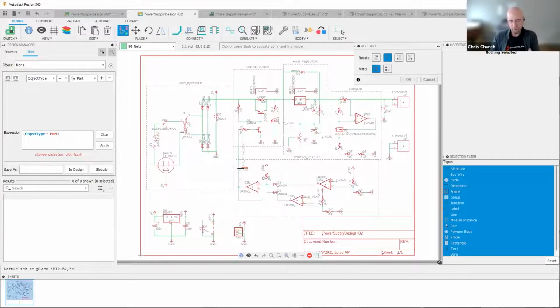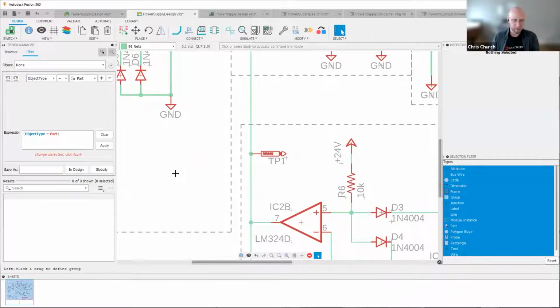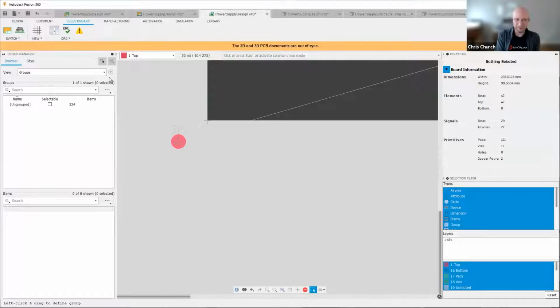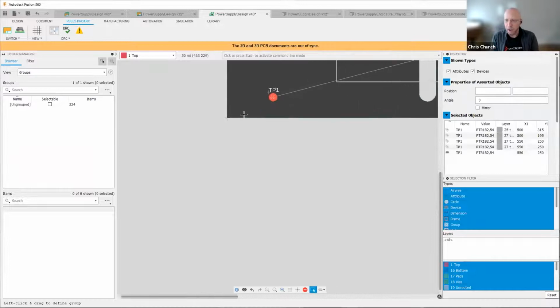But typical labor rates, if we're thinking US, run around $1 a minute at different factories. So for every minute of test, you're adding $1 to the device cost. So if we can work with you and build a test fixture for $15,000, does it save 15,000 minutes over the course of your production? That's really what we're going to be looking at there, is kind of the life cycle of the product, how much time we're saving, et cetera.